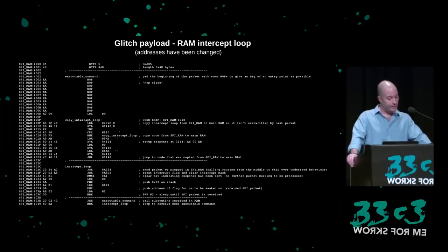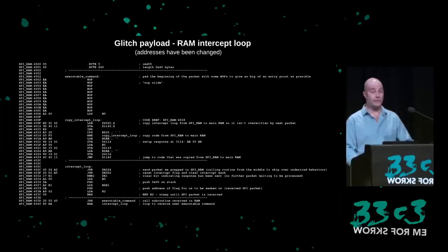The ACP operates from an internal clock source, and the interrupt-driven task switching does add some further timing uncertainty. So I will send the code payload, delay, then glitch, and see the result. When it's unsuccessful, I change the delay and I try again. I try to aim for the instruction that I've identified as possibly corruptible into a jump, but there are a lot of unknowns, so really the process is like fishing. Throw it a line and hope. I have a target, but no way to know if I can really hit it or if it will have the expected result. But sometimes fishing is good.